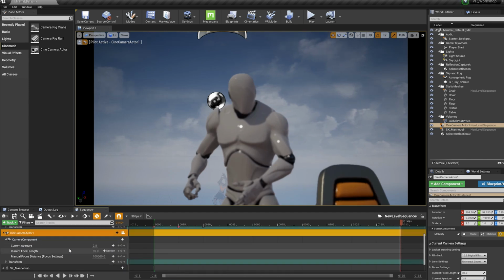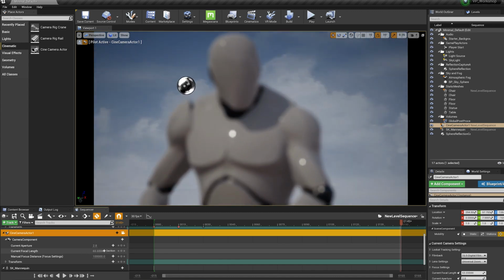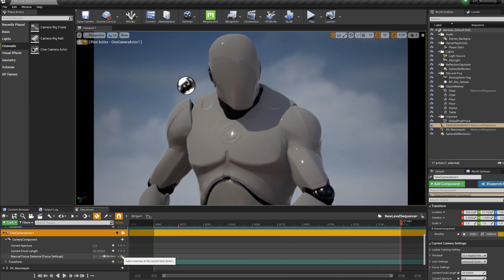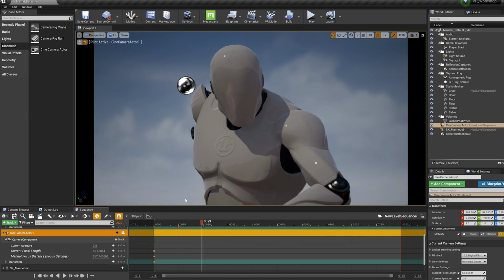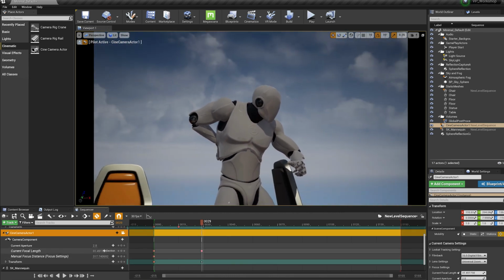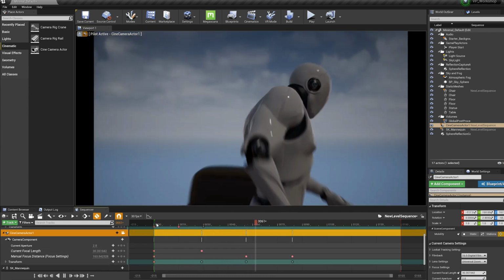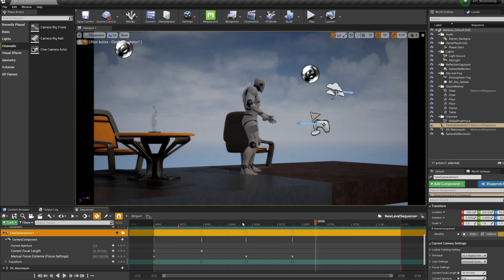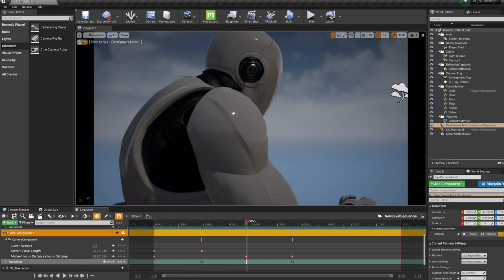As with the object transform earlier, you can also keyframe and control elements of your camera, such as the focus and focal length. With this, you can create animated camera moves, zoom pulls, and focus pulls. As default, the keyframe interpolation is set to cubic, which provides gradual smoothing between keyframes. To make these more direct movements, you can change this to linear by right-clicking on your keyframe.